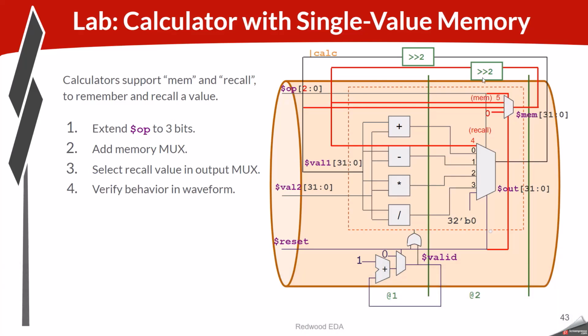We could actually do this with a 1-cycle loop as well. I'm just keeping this design all consistent with the 2-cycle cadence. So in this case, a value that we see in the memory on one particular cycle, if we're holding on to that value, we're going to see that value 2 cycles later after it's recirculated through this path.